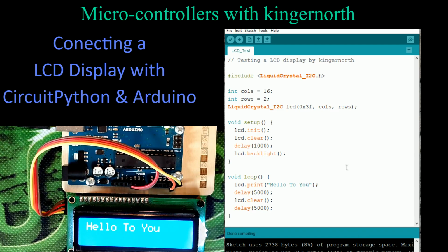So what we can do here is set something, and I'm going to change the position of my cursor. After this 5-second delay, I'm going to change the position of the cursor. So I can go LCD, and they have a function called setCursor. Oh, it's a small s in set, not capital. Then you give it a position of a column and row. I'm going to move it down to the next line, so I'm going to start with column 0, but move to row 1 this time.